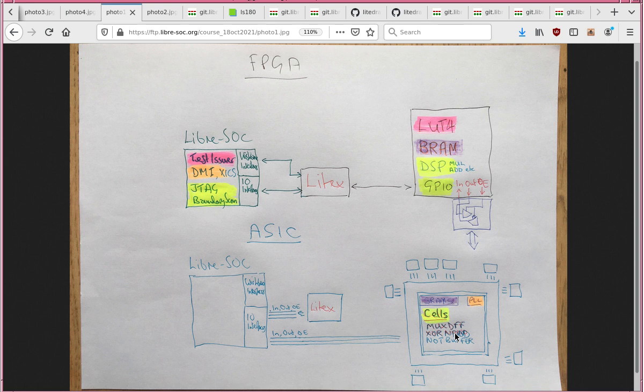As flip-flops are an extraordinarily inefficient way of doing things, but they're very, very fast. So you need them in some circumstances, but because the 4K SRAMs are so big, there's no way that we could do that, or we couldn't let Yosys do it, and so had to tell it, treat this as a black box, please.